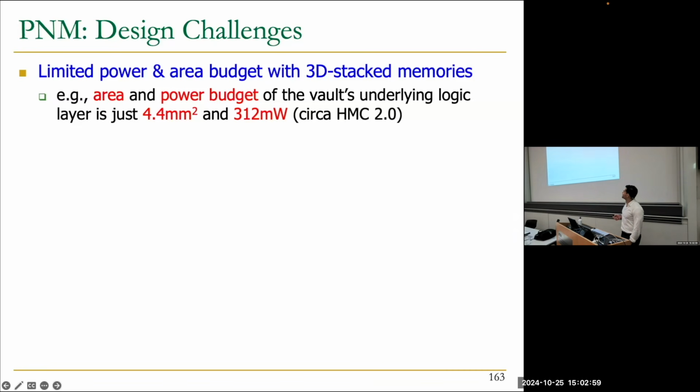But one good example here is that at the time there was a hype of designing processing-in-memory architectures around 2013 to 2020 using this architecture called HMC. This does not exist anymore, but you still have these HBM chips now. They are quite similar in scope, but basically those chips had 3D stacking of DRAM layers with a logic-based die. And in this logic-based die, you could put some computation.